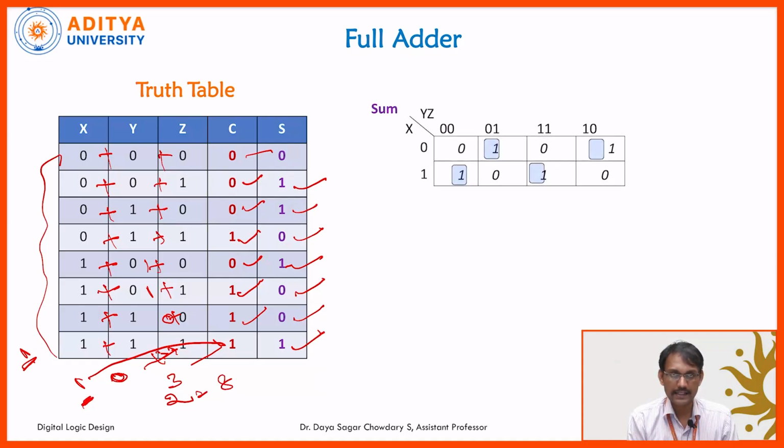So the next is we have to construct the circuit diagrams. For circuit diagrams we have to use the K maps, Karnaugh maps, we already know. So K maps for S and for C. So this is the sum part K map. Totally 8 combinations, that is why we are using 8 blocks, with the representation of 0 0 0, 0 0 1.